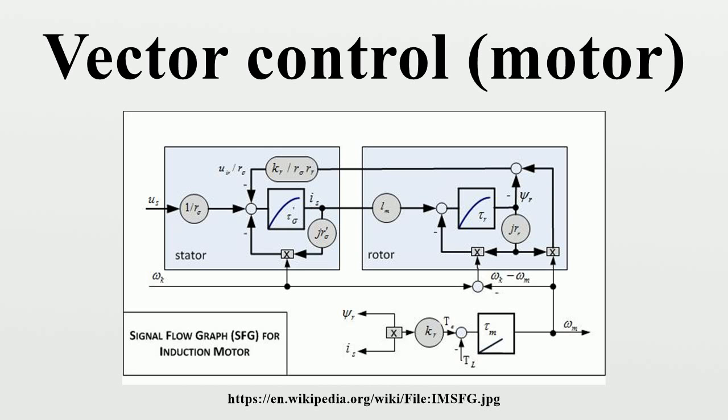Application recap. 1. Stator phase currents are measured and converted to a complex space vector in the stationary coordinate system. 2. The current vector is converted to a coordinate system rotating in the rotor reference frame, rotor position being derived by integrating the speed by means of a speed measurement sensor. 3. The rotor flux linkage vector is estimated by multiplying the stator current vector with magnetizing inductance Lm and low-pass filtering the result with the rotor no-load time constant Lr/Rr, namely the rotor inductance to rotor resistance ratio.